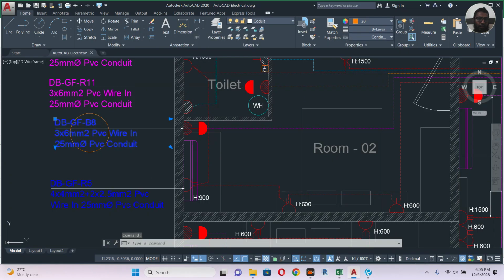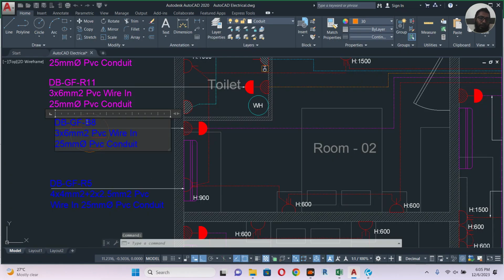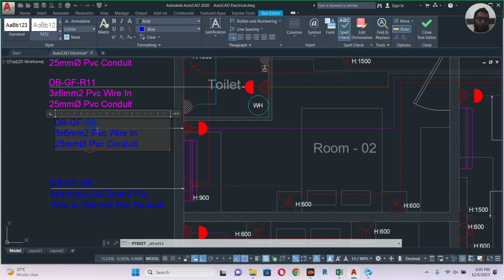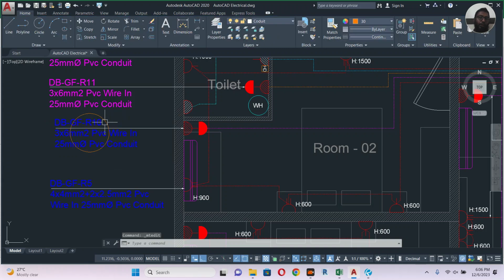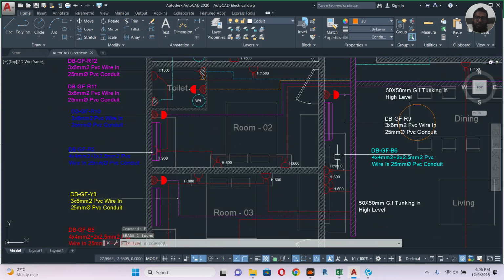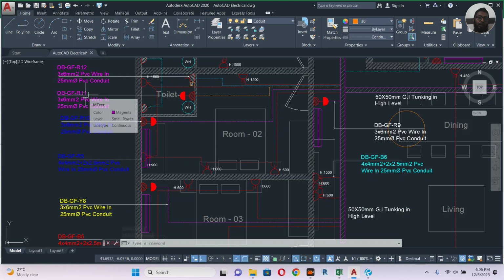So now, this is how we are balancing the DB. Too many people don't know how to balance DB. This is the way. R10, caps lock, R10. To balance the DB, you don't have to repeat the same circuit. You can change the circuit also. Let's say I have a higher load in the red one and lower load in the Y one. So I can make one of these Y color, yellow, maybe yellow Y11 or something, and I can balance the DB. Then we have to reprint and give it to the people who are working on this. I change the circuiting number to balance the load.